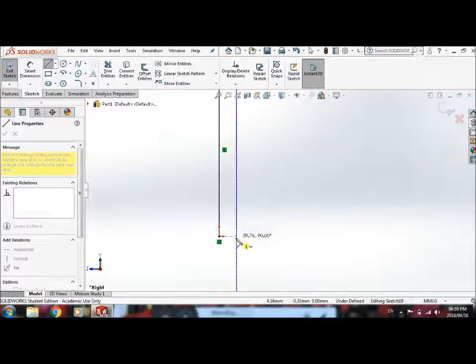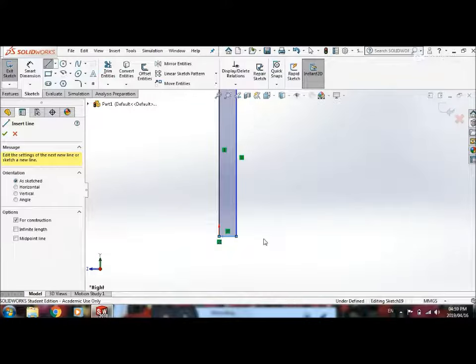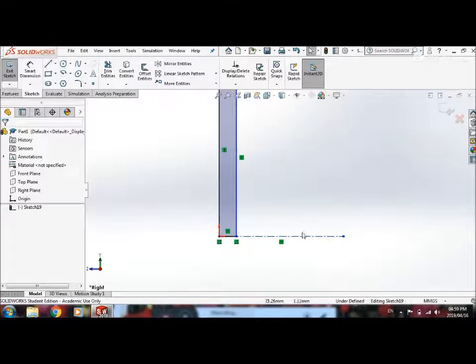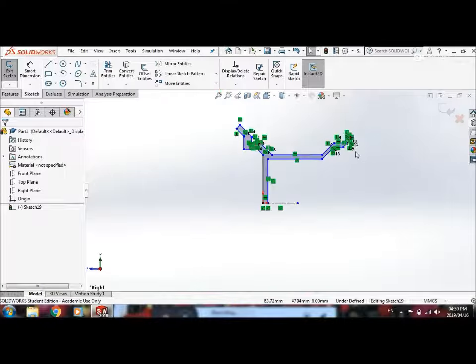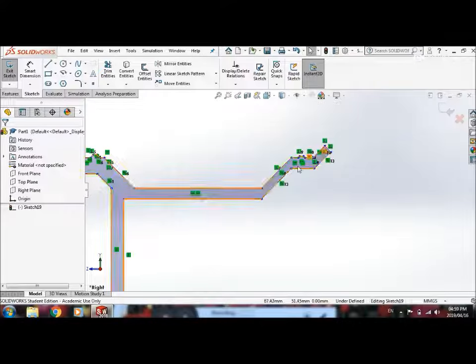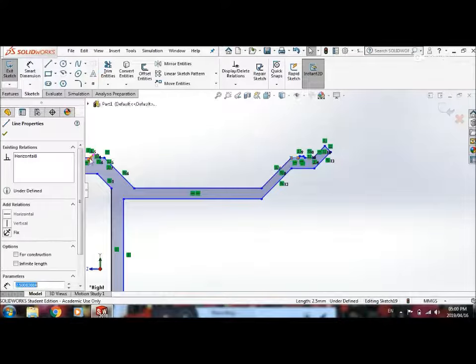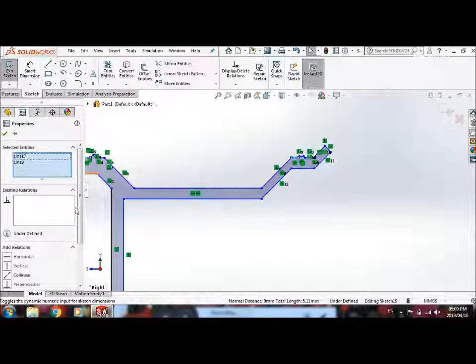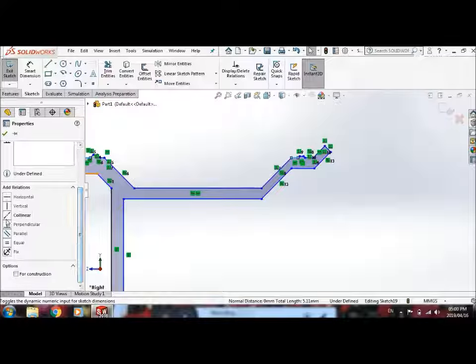Okay, obviously I'm just guessing these dimensions at the moment. Give it a rotational axis. Okay, my wheel is not very well aligned. So to add a constraint to a sketch, you can click on one line, then hold Control and click on another line. And then that allows you to add different constraints.